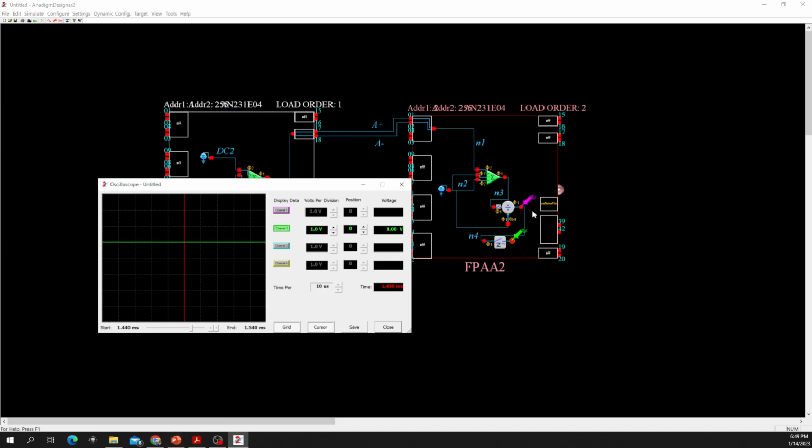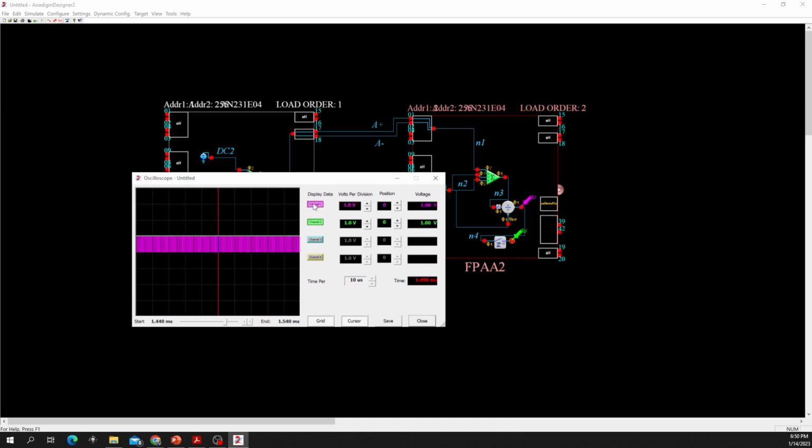So why do I have another pink one? I would like to show you, so just recall from my previous tutorials that phase 1 is only valid for a single phase. That means one clock period equals the amount of time phase 1 takes plus the amount of time phase 2 takes. So comparing the green output and the pink output, from our expectation, half of the pink one should be 1 volt and the other half should be 0, since it is invalid at phase 2. Let's see what happens. Let's zoom in a bit. The green one and the pink one are both 1, and at the next phase the green one is still 1, but the pink one is 0, which corresponds to our hypothesis.